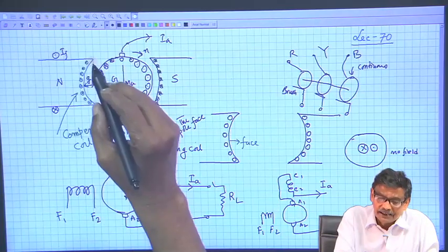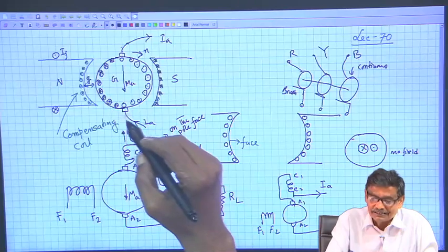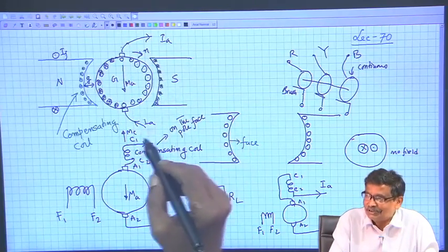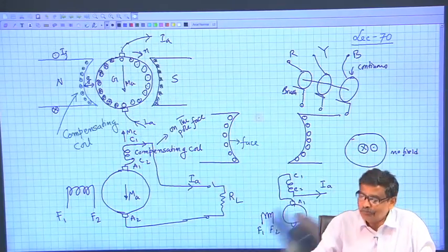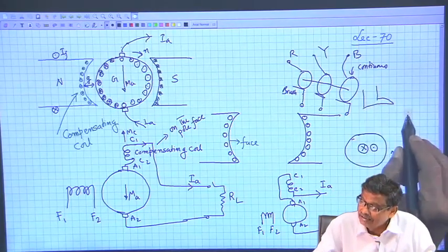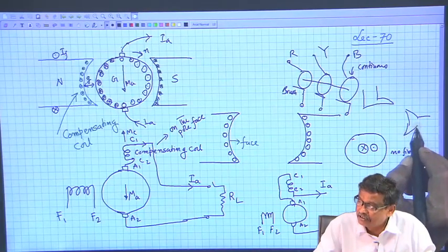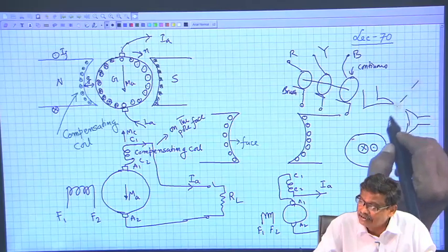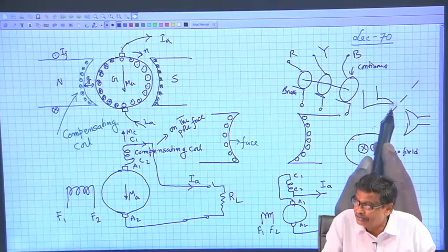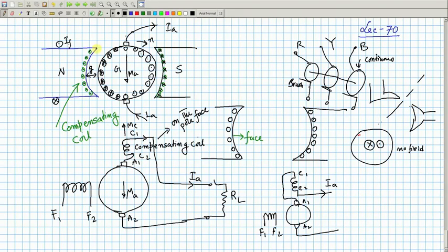because see, the pole face only extends not up to this zone, the pole is there from this to this. While calculating pole pitch, this is one pole, then there is another pole here, I drew it, flux per pole calculation, this is the magnetic neutral axis. So, in this zone, armature conductors are there, up to this point, but after that also cross dot is there.